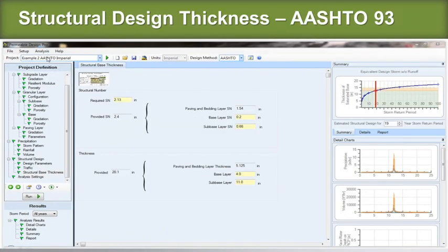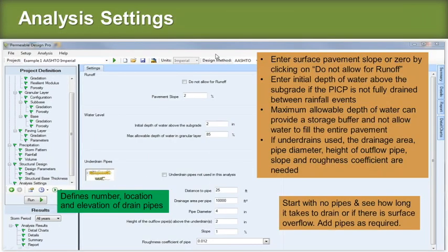Yeah, so then it goes, let me just interject something here. The beauty of introducing the pipes, say, for a partial infiltration design, where you're infiltrating some water and what you can't infiltrate, you drain out, is that you can vary, as it says on the screen, the pipe diameter, the spacing, and certainly the height above the subgrade. And typically I've just played around and done sensitivity analysis until I get the right amount of water that I need to capture.